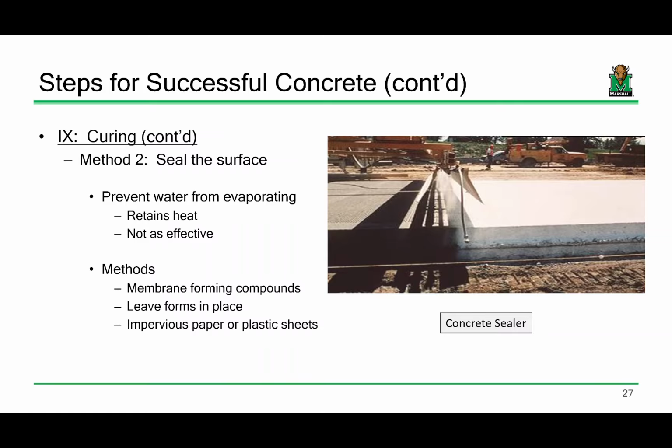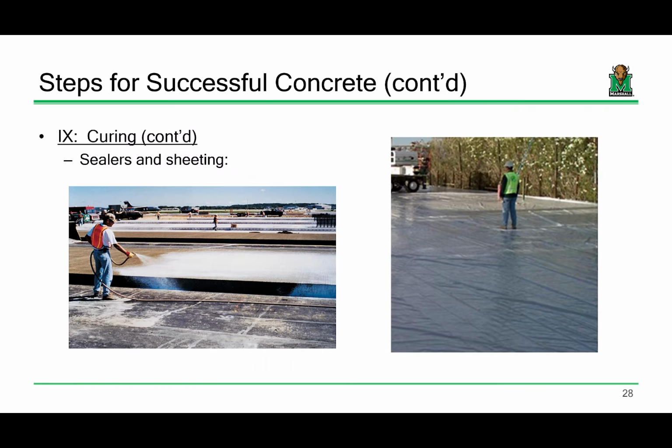If you've got a concrete placement with a lot of surface that's exposed, using some sort of spraying compound is simple. I'll give you that. You can see here some sealers. You can also use plastic sheeting, probably not as common for super big jobs, but it is happening.